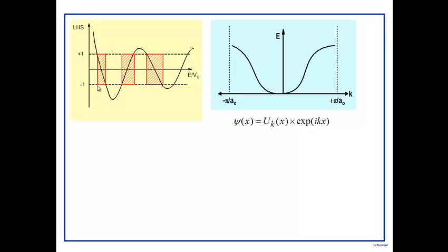As you would expect, all the electrons that are there in my lattice would now occupy this series of bands. Like in an atom, where it fills up 1s, 2s, 2p, 3s and so on. Similarly, the total number of electrons that I will have will first occupy all the lowest energy levels. Once they're full, they'll go ahead and occupy the next band. After this is full, they'll occupy the next, filling up from lower to higher bands.